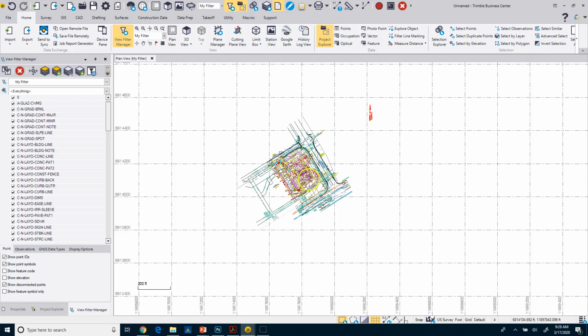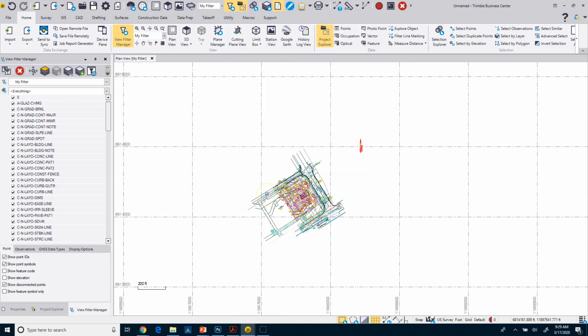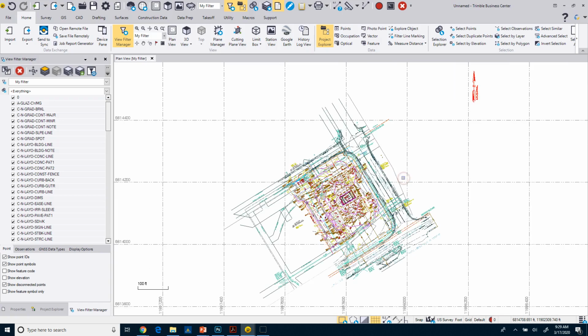By clicking that, it deselects the objects I've selected and selects the rest, and you can see down here that there are 4 objects selected that are probably garbage. So I'm just going to click delete and remove those. Now when I double click my wheel mouse, it does a zoom extents. It now will bring me back to here, and my drawing won't be out in the middle of nowhere.